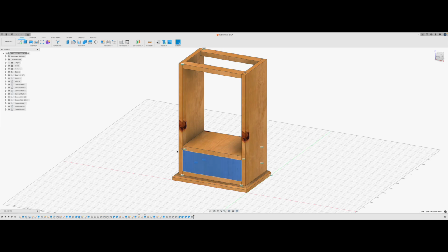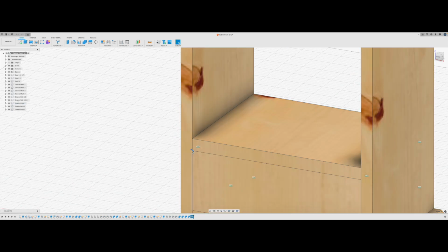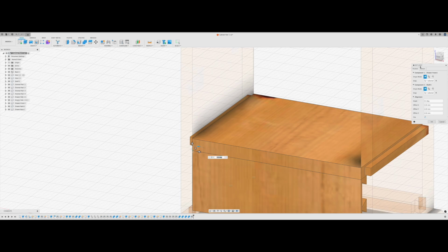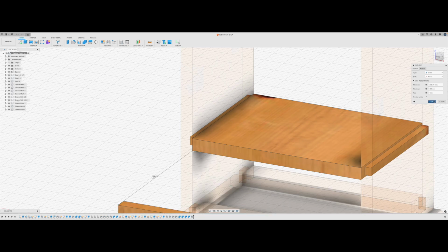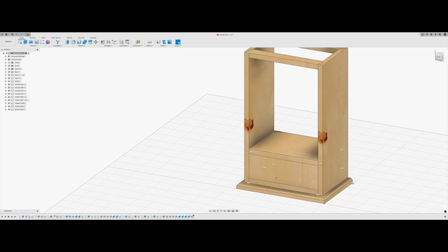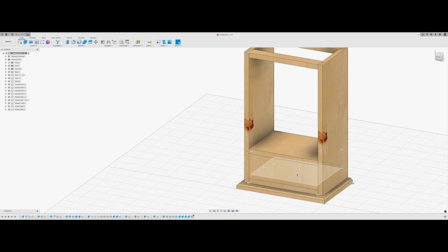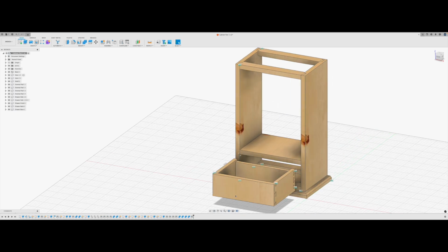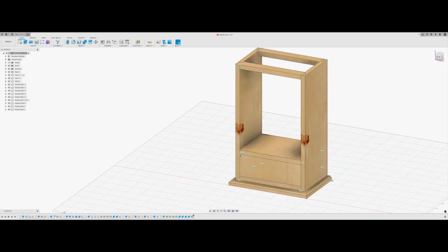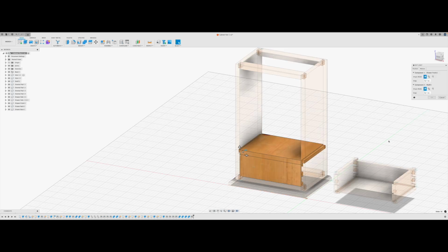So if I go back into that joint, which is that little symbol there that's changed, edit joint, I go to motion, I might just make him 200. So minus 200, and then he'll come all the way out nice and easy for me. And he'll stop there, and he can go back in. Now he does just automatically go back in without me dragging him back in there.